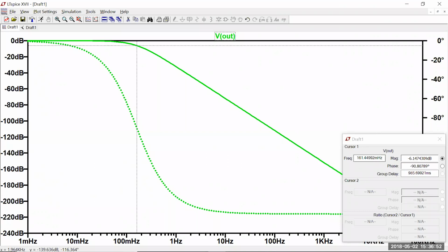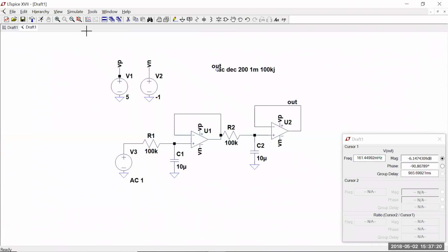And the frequency is 161 millihertz. I gave omega naught as 1, so the frequency is 1 divided by 2 pi. Now you might see in a lot of my examples, I work it out so that it's a nice even number to read off of the chart. All right, that seems to verify that what I was doing was correct.